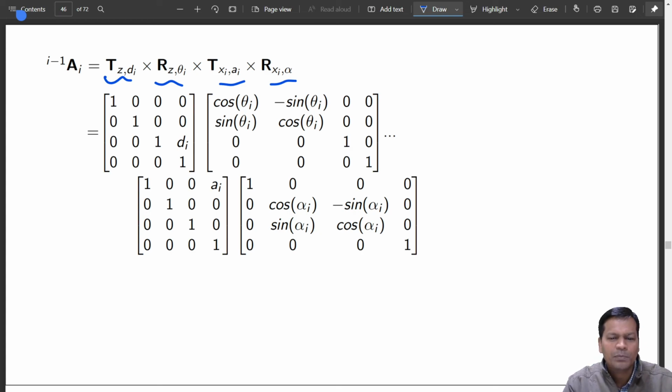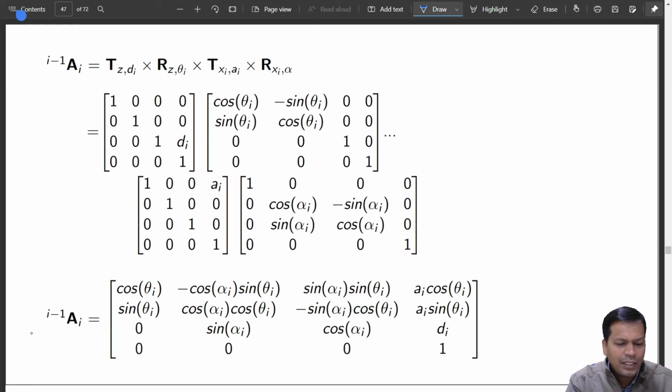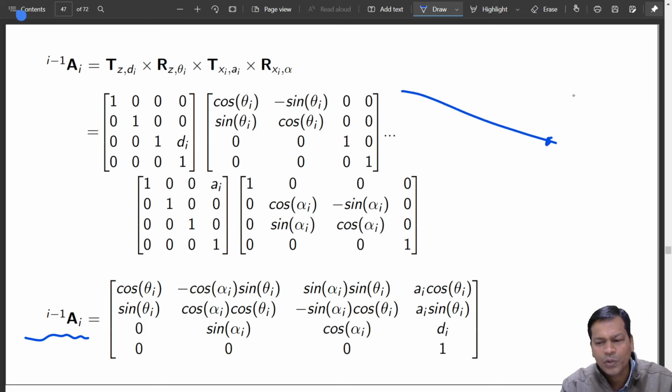You have to do post multiplication because it is on top of where you are already. Okay, you are not doing a global transformation. So this is your four transformations that you have done. Multiply them, you get a link transformation matrix which effectively takes you from this link joint to this link, this point.